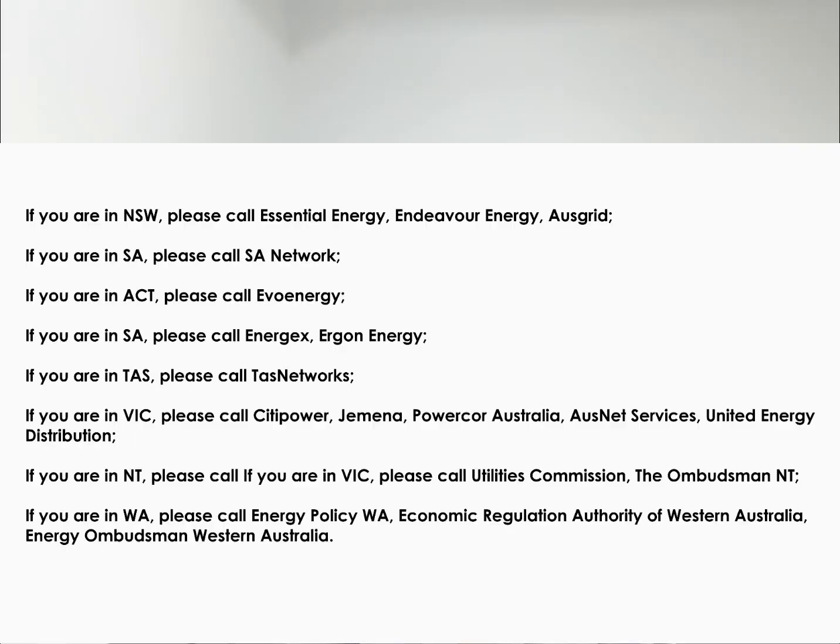2. You can call your electricity distributor to drop down grid voltage from the transformer. 3. Installers select the grid region area when testing and commissioning and adjust to the max voltage that is allowed in correspondence with that area. 4. Use the best inverter brand to avoid misjudgment of overvoltage. Install AC cable and breaker properly.